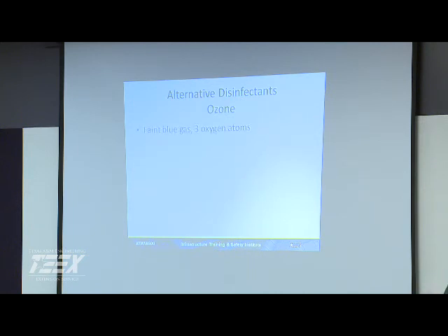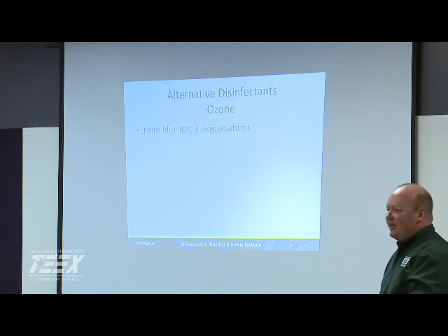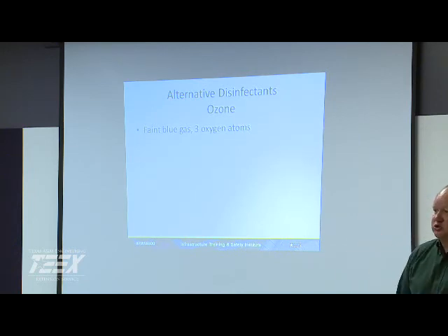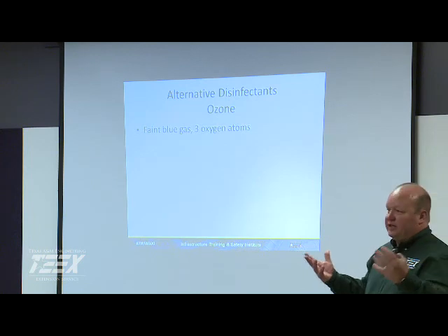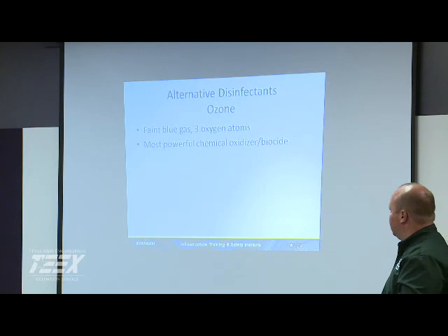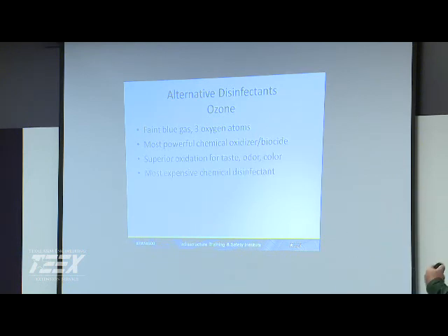Ozone, superb, awesome. I don't think we've got any systems using those anymore. Arizona is using a bunch of that. I guess they got deep pockets, I don't know. But they're using some of that as some of their pre-treatment. But it has to be generated on site, really, really powerful. But no residual is left, and it takes a good bit of expertise in running the system.